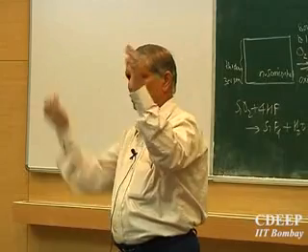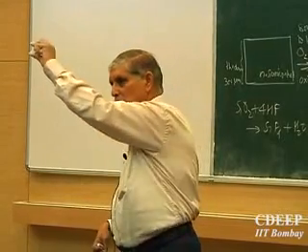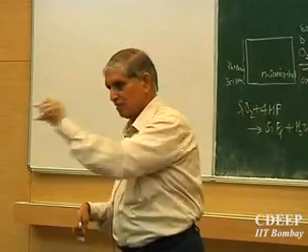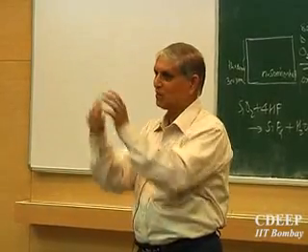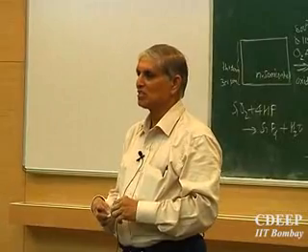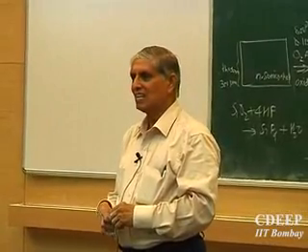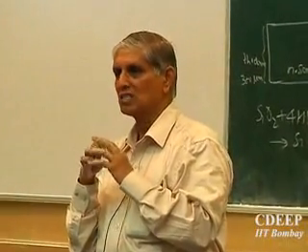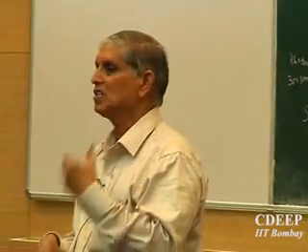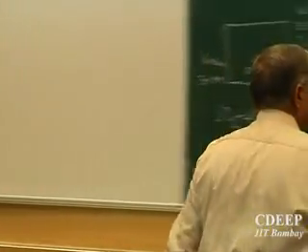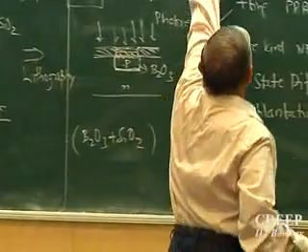So if you have a bigger wafer, you may start on the top row and keep going. And as many times as you do this, as many impurities you can introduce inside. Is that clear? This is called ion implantation. This is the process we use nowadays. No one uses solid state diffusion. This is the process. Before we quit, last word, how will it look?